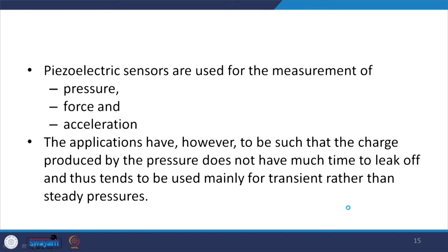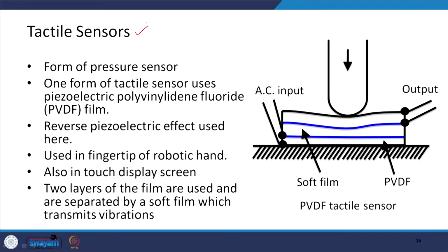Now, piezoelectric sensors are used for the measurement of pressure, as I have already told. They can also be used for the measurement of forces as well as acceleration. The applications have to be such that the charge produced by the pressure does not have much time to leak off, and thus they tend to be used mainly for transient pressure rather than for steady state pressure. Next, let us look at the tactile sensors.